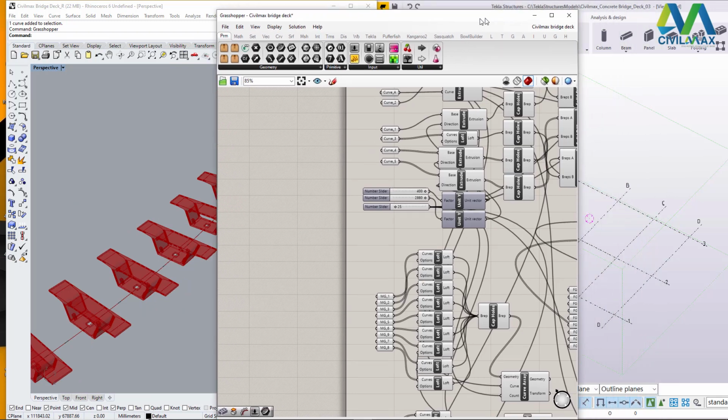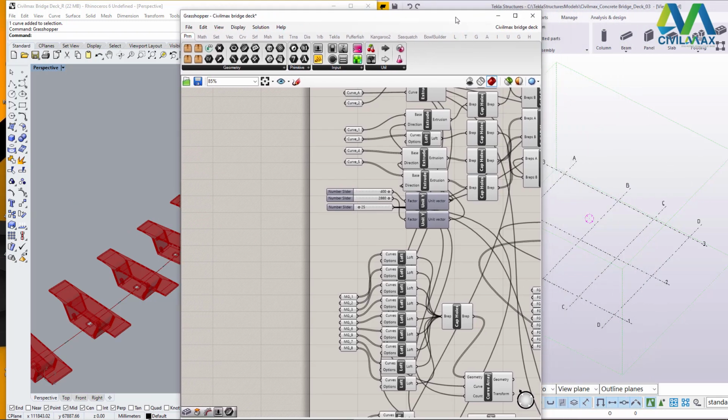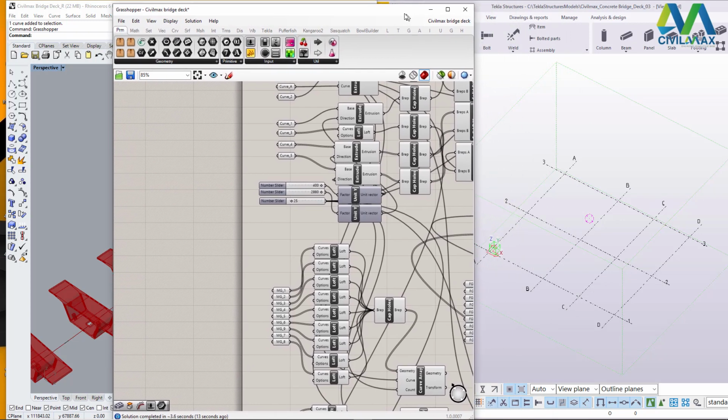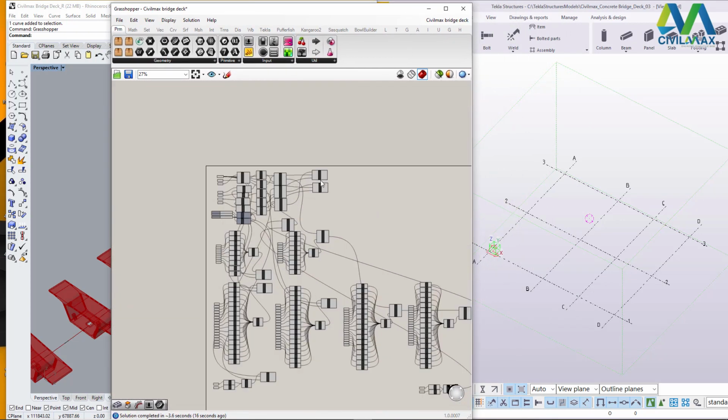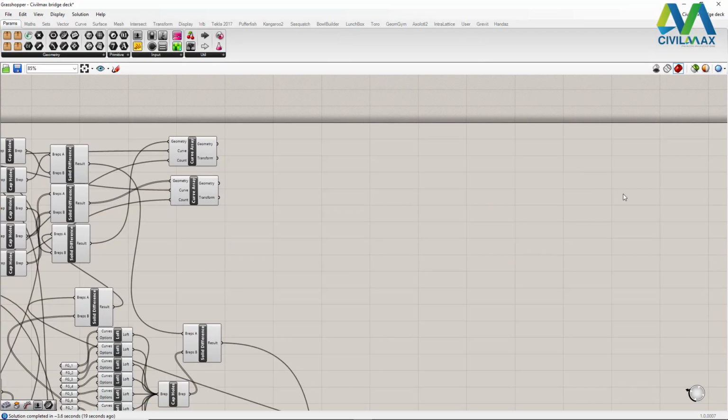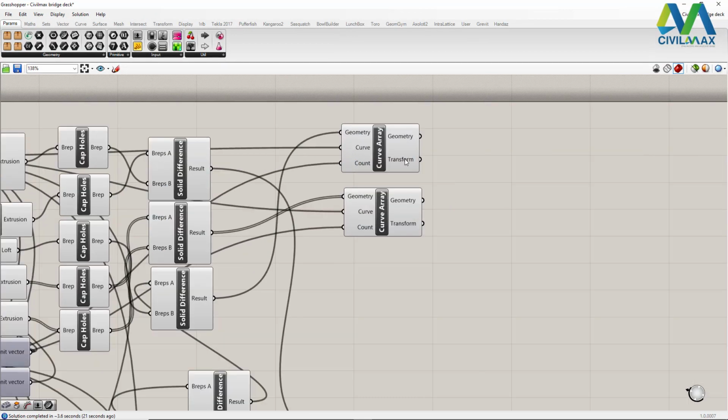Now we want to take everything to Tekla structures so that we can do more about this. So what I'll do, I'll first of all make this a little bit bigger. To connect this, you can take a look on my menu bar. I have a variety of what I can do. I can link up with Revit by using all this. I can also interpolate with Revit straight. I can take this model straight to Revit, and also have all this.